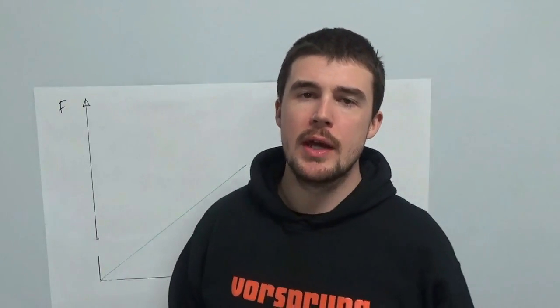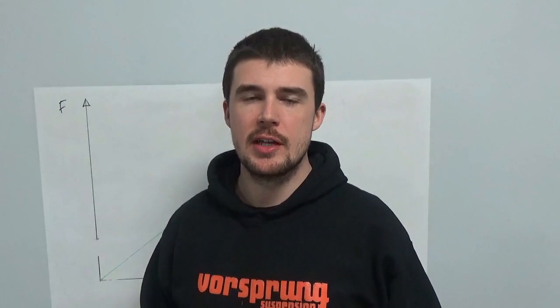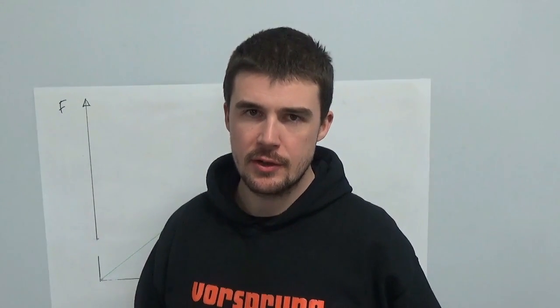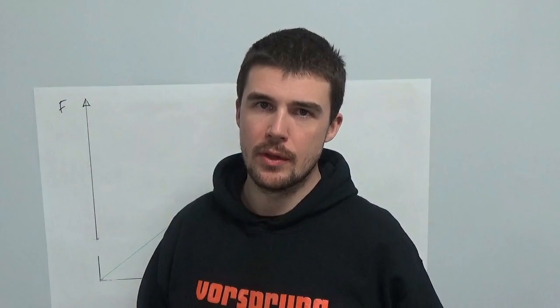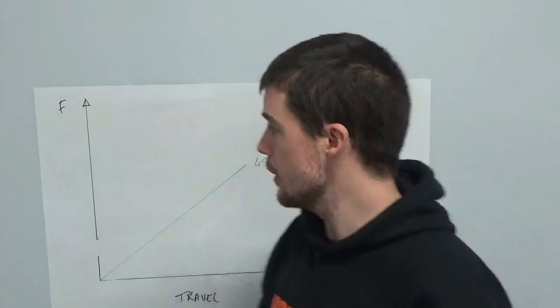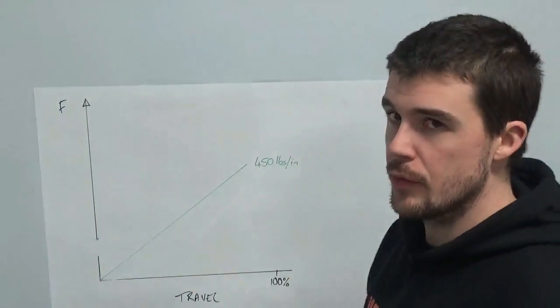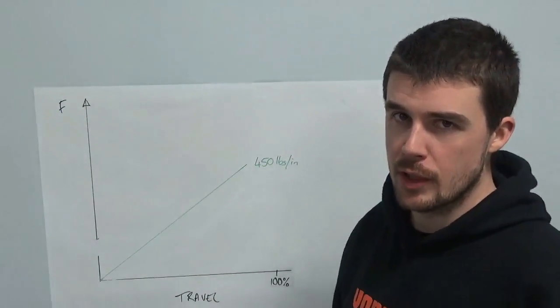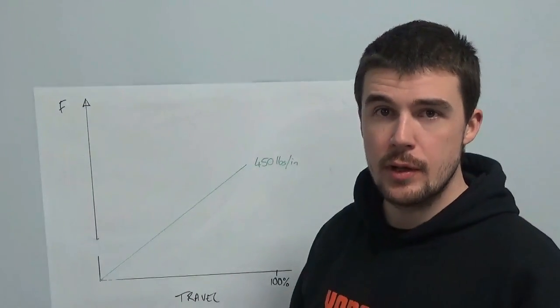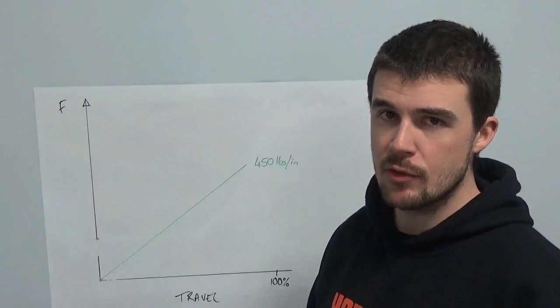Number two, we quite commonly get asked about this. Do titanium springs perform better than steel springs? The simple answer is, if weight alone is your metric of performance, yes. If it is anything else, no, they are essentially identical. They do not respond faster, they are not plusher. A spring rate is a spring rate. This is a 450 pound-per-inch steel coil spring. This is also a 450 pound-per-inch titanium spring.